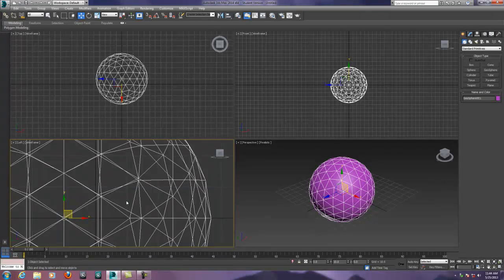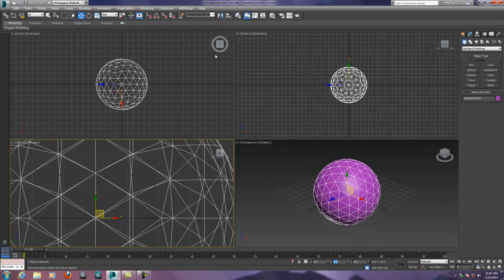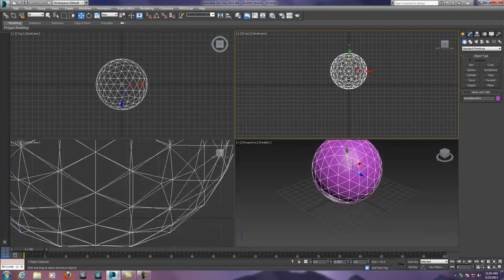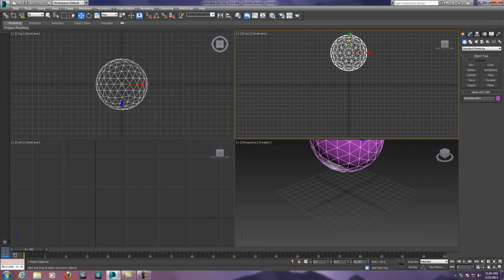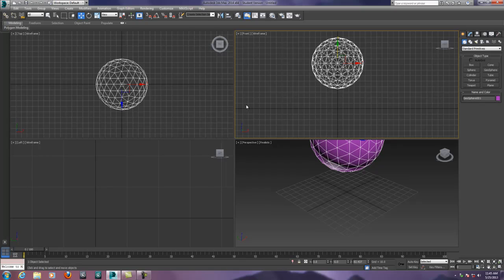That's the tricky part about 3D, is depending on how the object was created, its X, Y, and Z could be different. So a lot of times, to help you out with this, we're going to be using really free-form moving, rotating, and scaling of objects. So if I move this up where I actually want it in the front view, so if this was the ground and I'm moving this up, you'll notice down here that it actually moved it in the Z direction of that object.